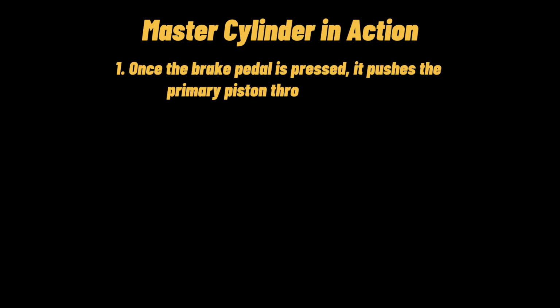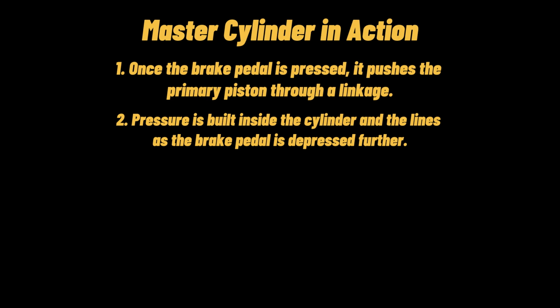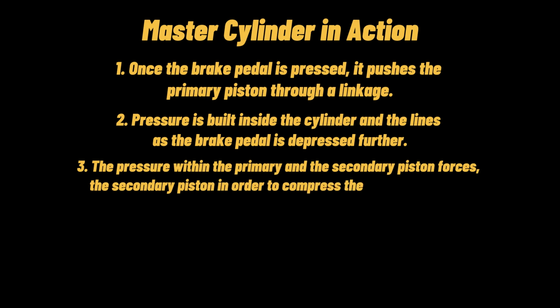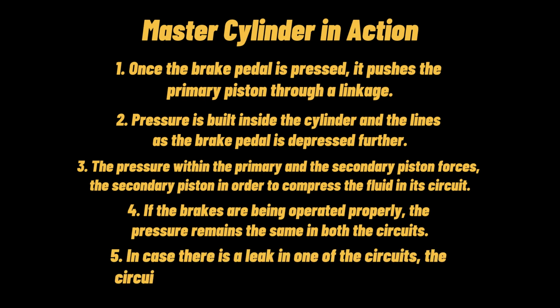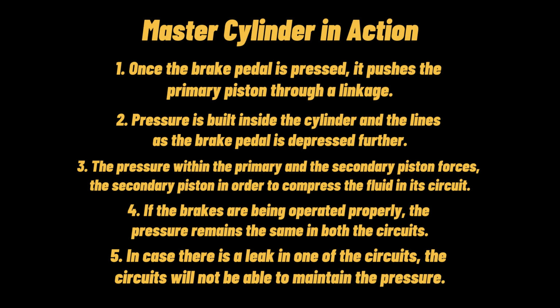Master cylinder in action. 1. Once the brake pedal is pressed, it pushes the primary piston through a linkage. 2. Pressure is built inside the cylinder and the lines as the brake pedal is depressed further. 3. The pressure within the primary piston forces the secondary piston in order to compress the fluid in its circuit. 4. If the brakes are operating properly, the pressure remains the same in both circuits. 5. In case there is a leak in one of the circuits, it will not be able to maintain the pressure.